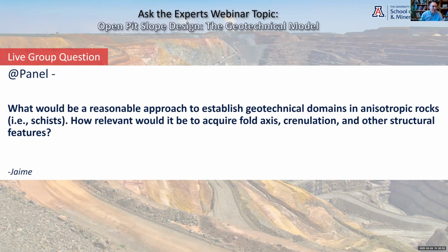Just to add one more thing onto what Lauren said, if you're working with borehole data in a deposit like this, in a rock type that's extremely anisotropic, you really need to be careful about watching the blind zones in your televiewer drill holes. Basically, if you drill a televiewer hole, you're not going to be able to see structures that are parallel to the borehole. That'll be the big blind zone. And then there'll also be a smaller blind zone that's perfectly perpendicular to the televiewer hole.